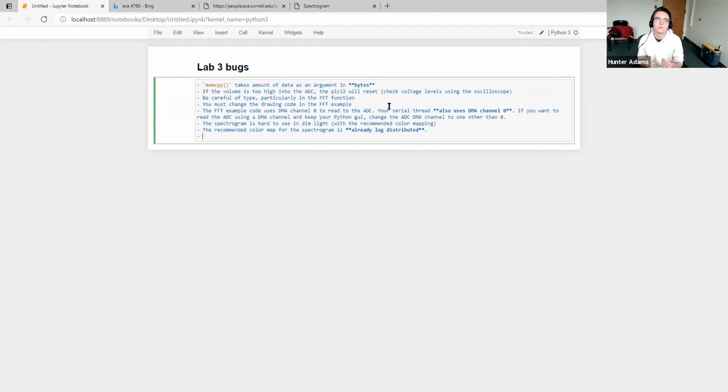One of the requirements for this lab, and specifically for the week 1 checkout, is computation of the frequency with max amplitude. I need to be careful with my language here. So not the maximum frequency, but the frequency where there is the most power in your spectrogram. You need to compute that and display it in some way. You can display it on the TFT if you want. You can print it out through the Python terminal if you want.